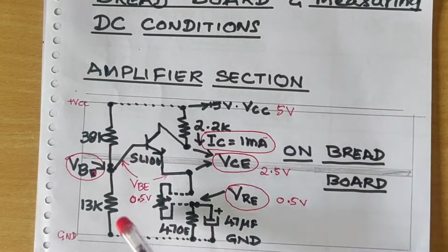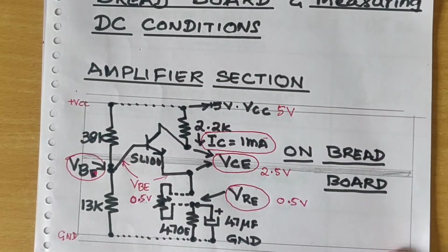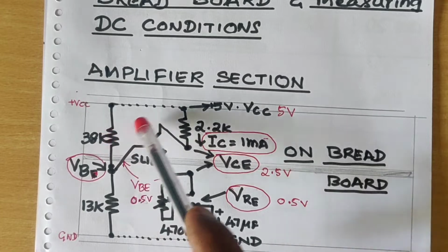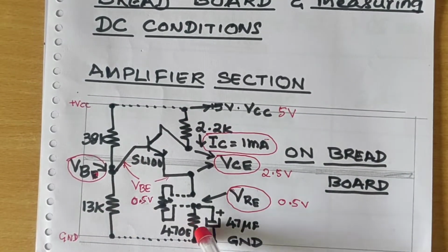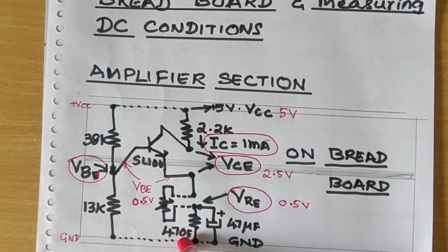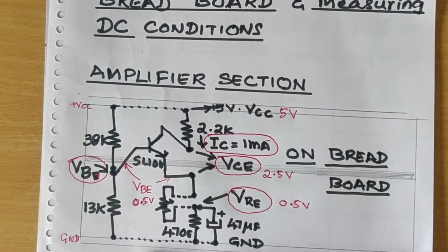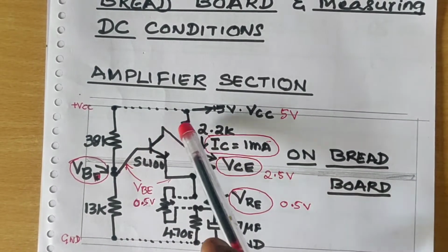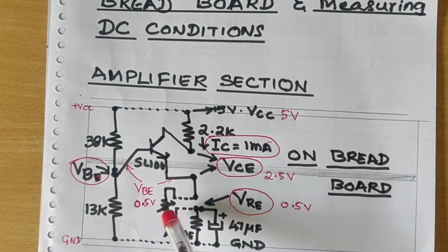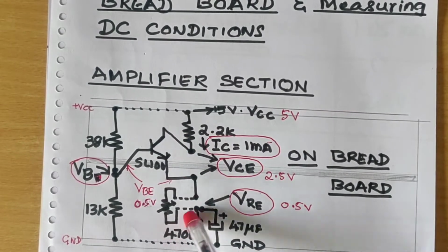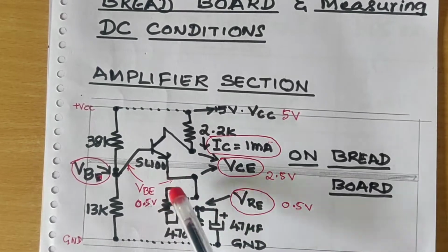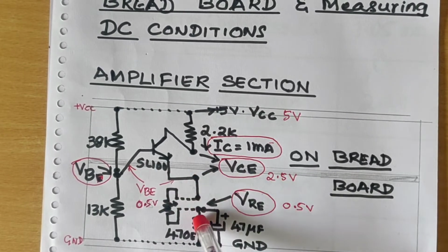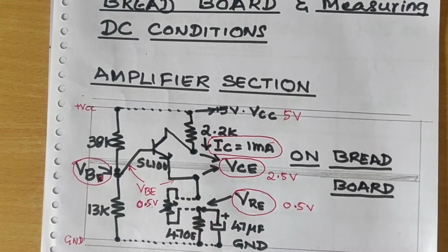So rig up as shown, assuming this is a breadboard, where R1 and RC are connected to the VCC line, and R2 and RE are connected to the ground line. Just connect the transistor base, collector and emitter as it is. The variable part is optional, used to get the output without any distortion, so we assume that we connect this directly to RE.